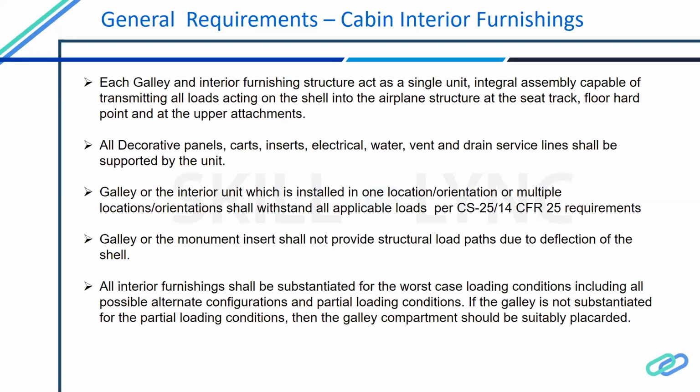Those are the generic requirements that we should keep in mind while designing this galley or a monument. One of the first of such requirements is that these galleys and monuments should be able to act as a single unit or an integral assembly, because when they are mounted to the aircraft, they are attached to the floor using the lower attachments, and they are attached to the airframe using the upper attachments.